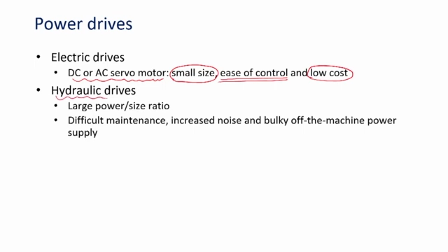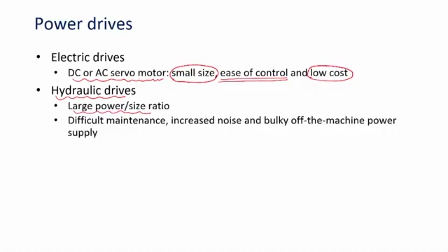Pneumatic drives are also being used, but these are for auxiliary purposes, for example cleaning purposes or actuation of some auxiliary operations such as closing or opening or changing of the tool in the CNC based machining operations. The CNC based laser machines are also classified based upon the positioning system.